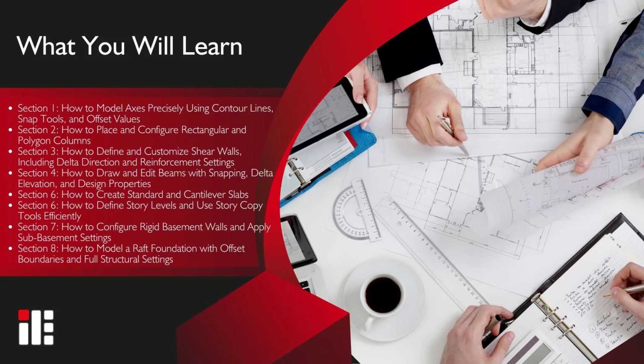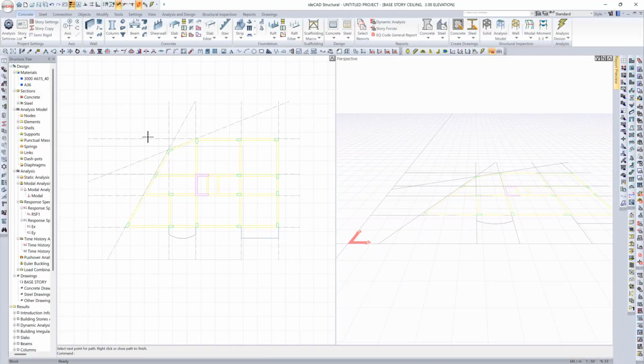After that, you'll define additional stories, copy modeled elements across floors, and configure rigid basement shear walls. Finally, we'll wrap up by modeling a raft foundation using route paths, offsets, and full structural detailing. By the end of this video, you'll be able to model all major structural elements with precision and confidence using ideCAD. Now that I know the units are correct, I can directly start axis modeling.